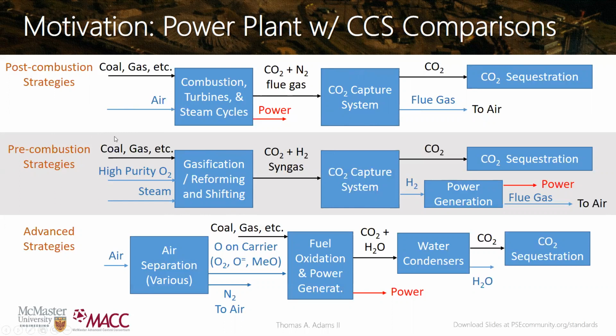All right, and the idea is that all of your carbon by this point is in CO2 form, and all of your hydrogen is in H2 form, and most of your energy that you started with in the fuel ends up in that H2. Okay, and there's lots of different ways you can do this. Primarily, usually you need a very high purity oxygen stream in one way or another. And there's lots of different technologies depending on the fuel, but ultimately you end up with the CO2 hydrogen separation problem. Okay, and you can do the same kind of approaches as the post-combustion.